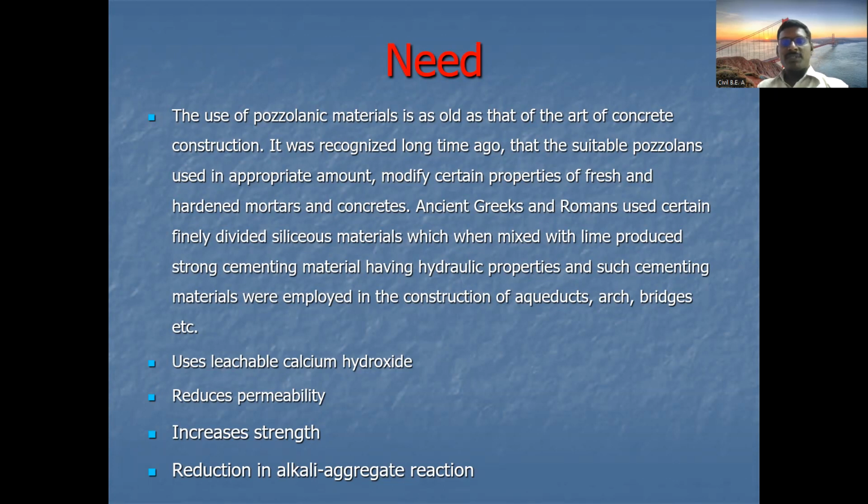In the construction of aqueducts, arch dams or bridges, etc., we use pozzolanic materials, because such aqueducts, arches or bridges are underwater constructions, or water is available during the construction of these structures. So why are these pozzolanic materials needed? Because the pozzolanic material uses the leachable calcium hydroxide.